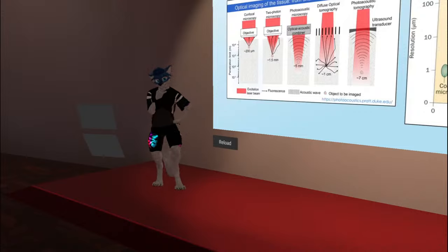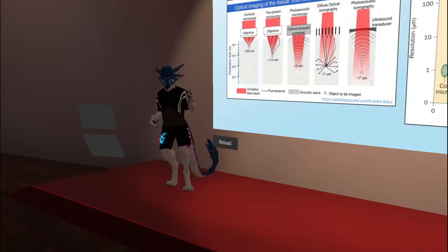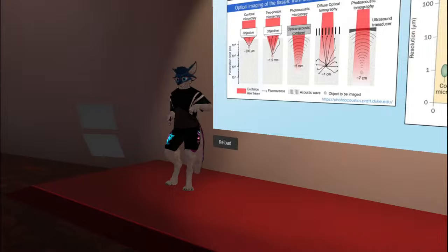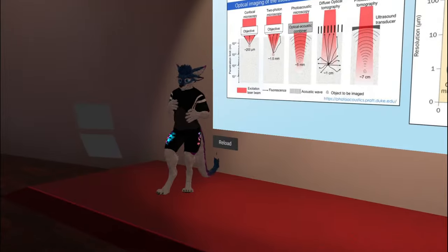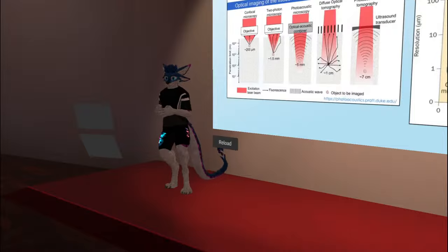Could have actually been a good thing to include here. You can also look up, if you search Corning or Schott, their glass tables. That's kind of a titular tool in the optic designer toolbox. There's, I think, almost 1,000 or so quote unquote commonly produced optic glasses. More common ones are probably a family of like 50 or so. But they really are just basic glass, just with different dopants and done to a much higher level of purity than, for example, window glass would be.